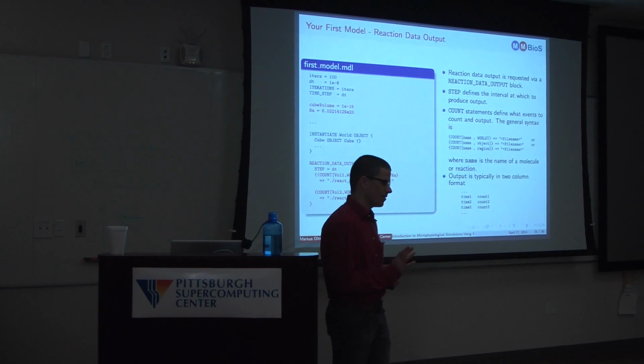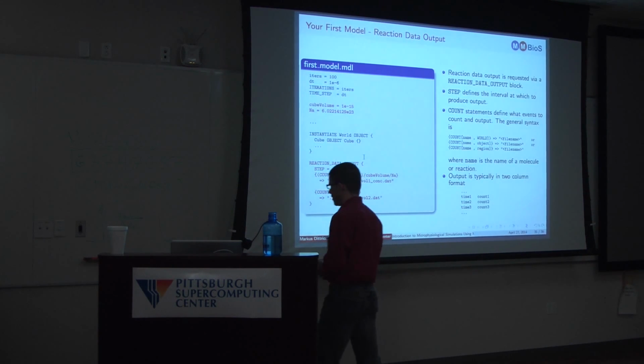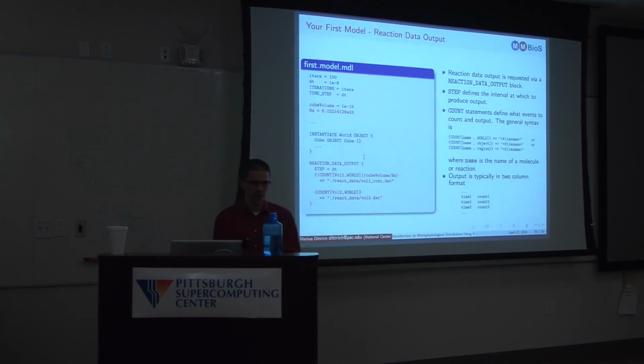But it's a good question. You remind me of something that I should have maybe mentioned. Keep that in mind if you run an MCell simulation. Again, it depends on your model, but it doesn't necessarily make sense to just run one simulation, look at your output and say, aha, it is 5, because it's just one. It's a stochastic process, and so you really should, most of the time, do some averaging of the quantities you're interested in.